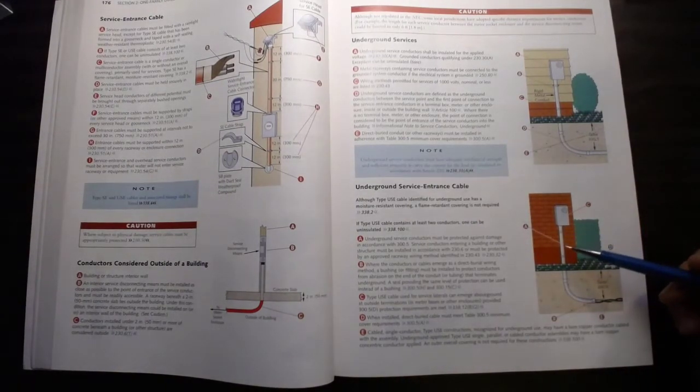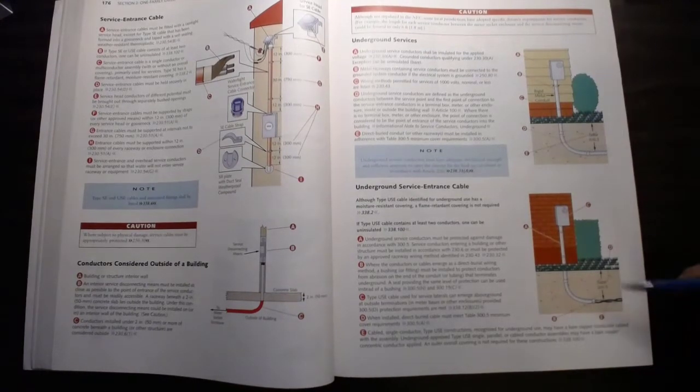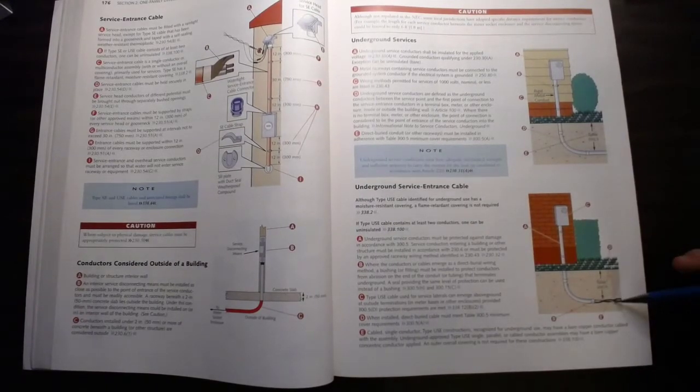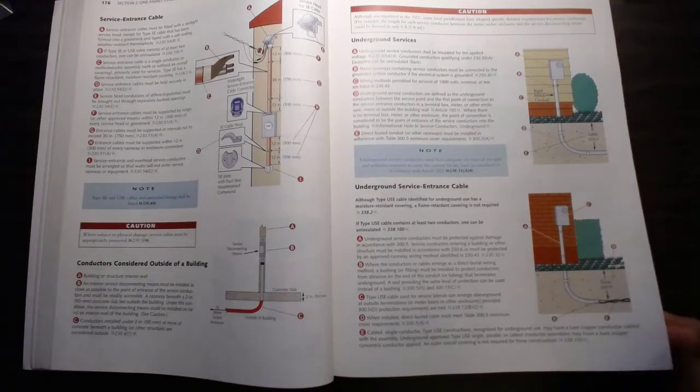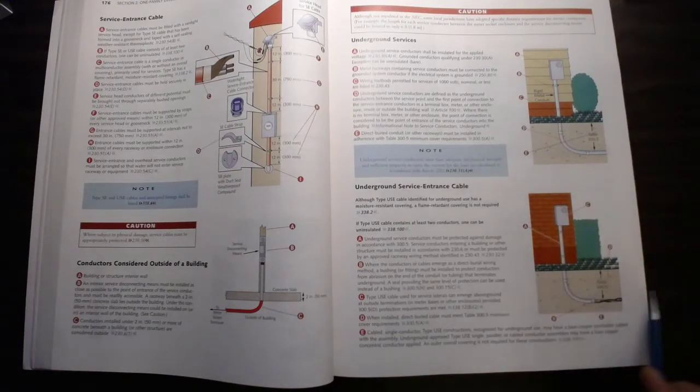In the case of having to use underground service cable, where it can be direct buried, you can use a conduit that just 90s out and heads the direction that you need to run. And you have to make sure that it is protected with a bushing, and then the direct buried cable can go right out into the earth at that point. In the 70s, 80s, and early 90s, direct buried cable was used quite often in track home construction and has been moved away from, at least from a utility service perspective. Everything's going to be in conduit because when this fails, it's a lot of money to repair that.